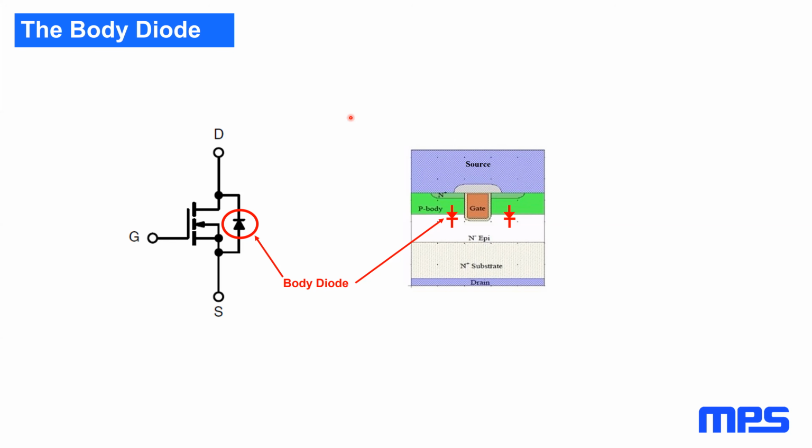Most are not. That said, the fact that MOSFETs have a lot of capacitance tends to make them a little less sensitive. It doesn't take much voltage to break it down, but it's a big cap, so it takes a fair amount of current to charge that cap to 20 volts. So bottom line is you still have to be careful.